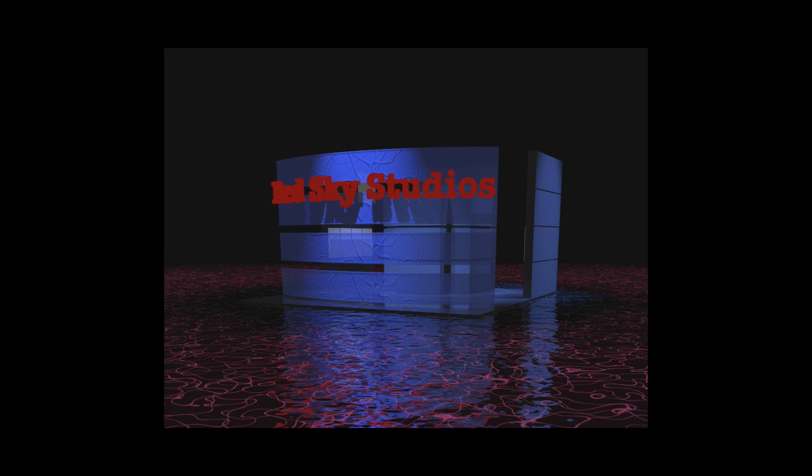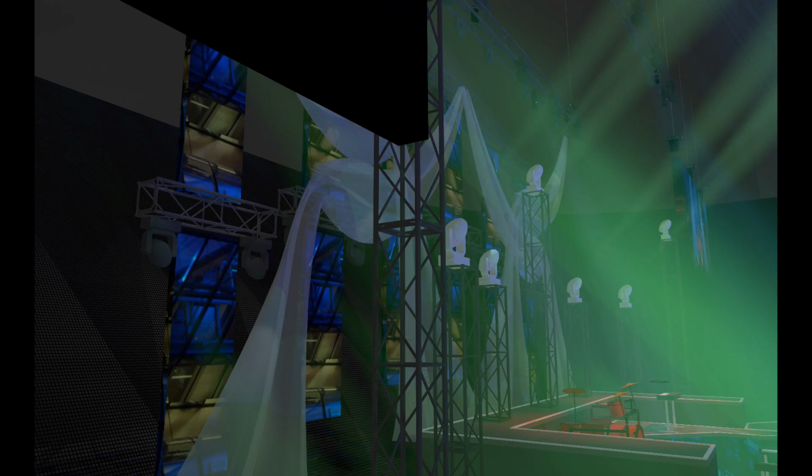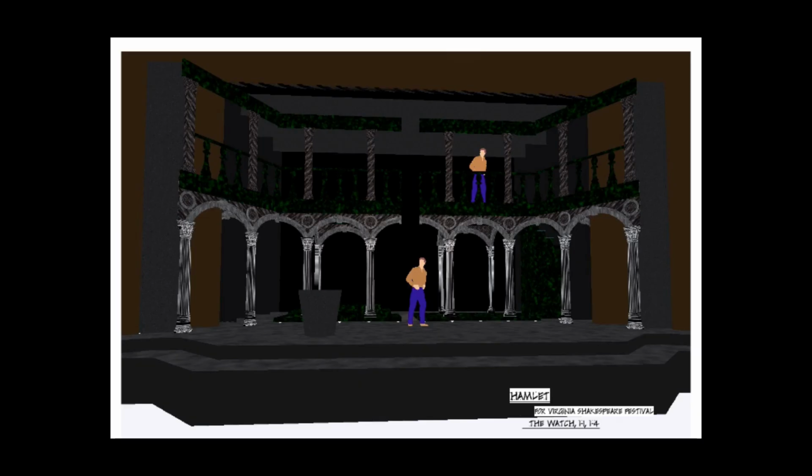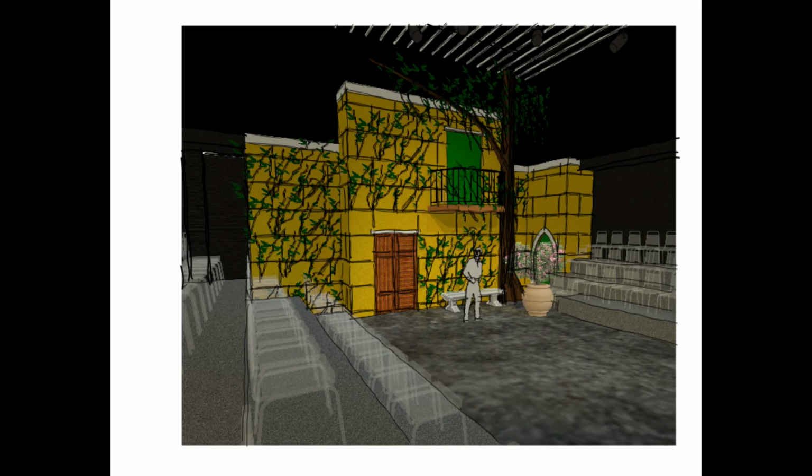baseline OpenGL to the more advanced settings in Custom Renderworks, where you can set up hazy environments that catch the light beams, create textures that suggest accurate materials with transparency, reflections, glowing elements, backlighting, and 3D textures with thickness that cast their own shadows without having to create the 3D geometry. Also, with our Renderworks camera, you can set projections to simulate most any camera.